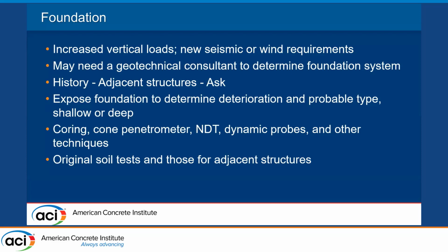So again, who do you ask? Well, you can expose the foundation to determine deterioration and probable type. Even we structural engineers can kind of do that. And you can core, use a spectrometer, some NDT stuff, but really you need the geotechnical engineers to say, in this area of town, we more than likely had spread footings on certain kind of soils because in this area we have certain soils, right?